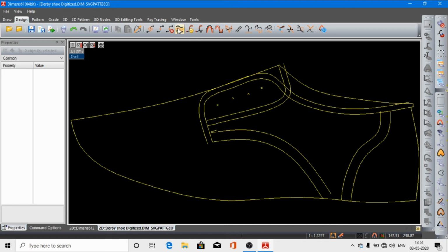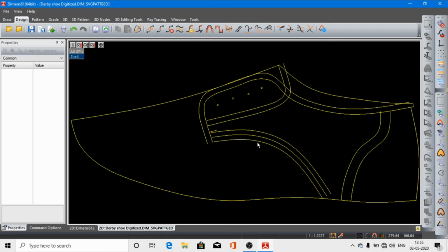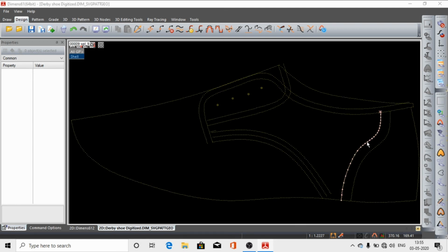Next, a very important part is that if you want to draw a middle line between two parallel lines, then you can use this. Suppose I have these two parallel lines, and we want to draw a middle parallel line. For that, we will go to this average to spline, left click over there, select the to spline, this one, and select this one, and go to OK. You can see that a new middle line has been developed between these two lines. It is very important while you are going to create any creative designs.